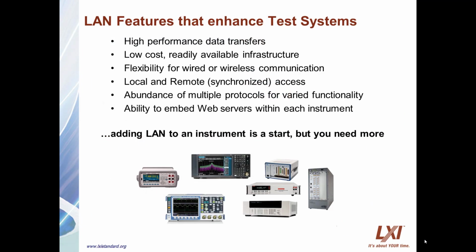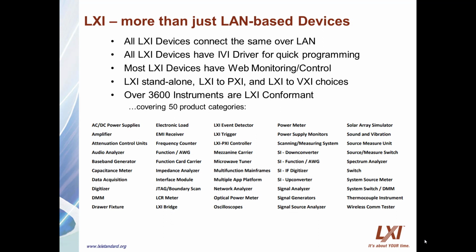LAN connectivity is common. Fast, inexpensive, reliable, all those features you want in a test system. However, adding LAN to an instrument does not mean all devices will work the same when connecting to the LAN. LXI, which stands for LAN Extensions for Instrumentation, is the standard for Ethernet control of instrumentation in the test and measurement industry. Prior to this standard, there were LAN-based instruments, but there were almost as many different ways of configuring those devices as there were products.